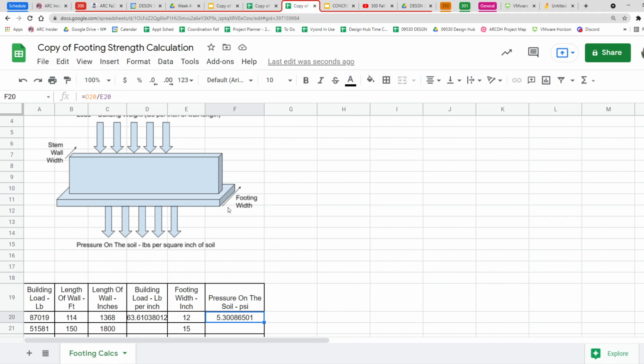Okay? And then that's the geotechnical person. That's what we did last week. We said, oh, I wonder what number my soil can carry. So depending on the Proctor test and the building pad and how it's compacted and everything, the architect or the structural engineer is going to design this. Now, what's really cool is, let's say somebody said, oh, my soil can only carry 4 pounds per square inch.